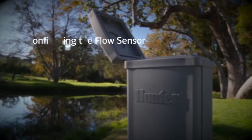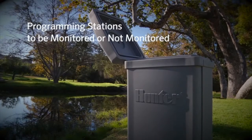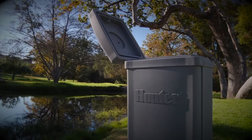We will also show you how to configure the flow sensor at the controller level, as well as how to program stations to be monitored or not monitored by the flow sensor. Finally, we will explain the process for learning flow and for setting up the overflow and underflow percentages.